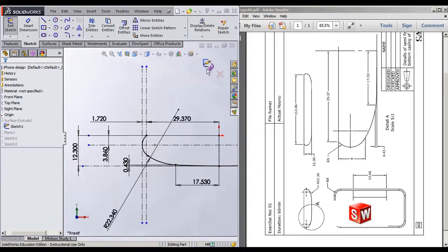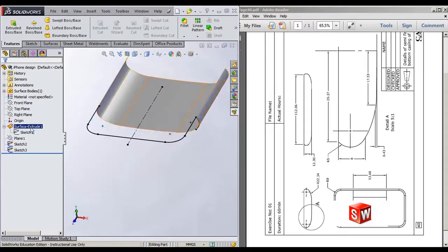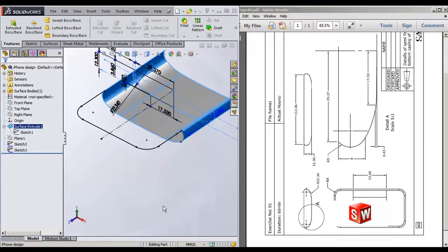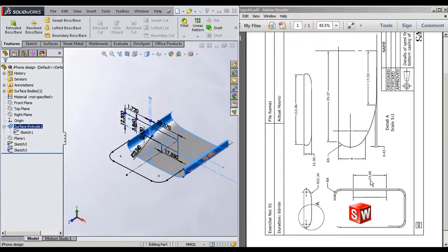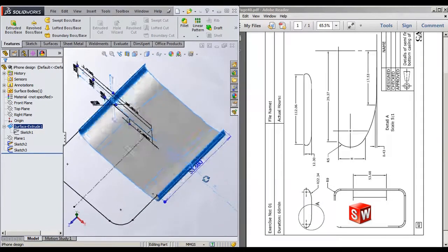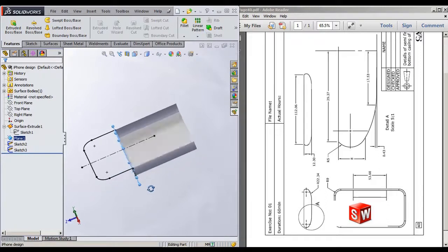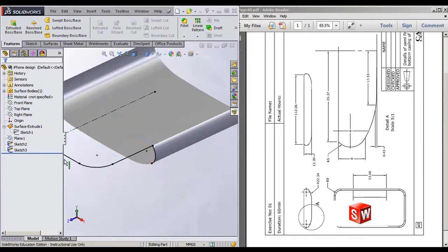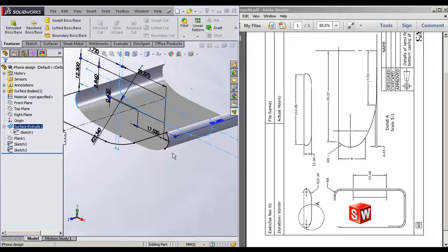Once you complete the sketch, we need to create an additional plane. Before that, we need to extrude this to some distance symmetrically on both sides of the plane. The extrude depth is given here, 53.68, so you can assume how much round-off value you want to give. Once this is completed, you can create a plane exactly coinciding with this edge, and on that plane sketch an arc exactly coinciding with this arc on this side.